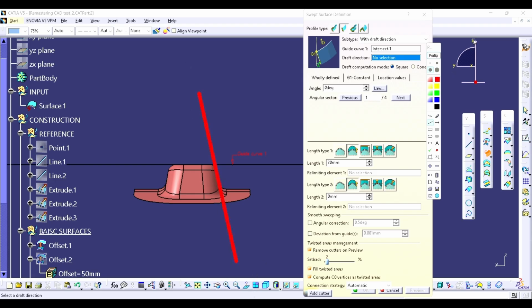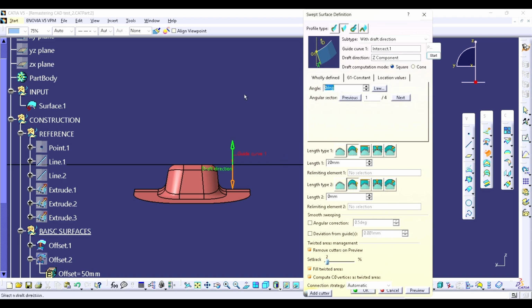For this we are required to provide the drop direction in Z. So I'm going to provide the drop direction as Z. Now the angle is 95. We have already measured it. So 90 plus 5 is equal to 95. So I'm going to give an angle of 5 here because we require it in Z. Here I'm going to change the lengths to 200 and 200.